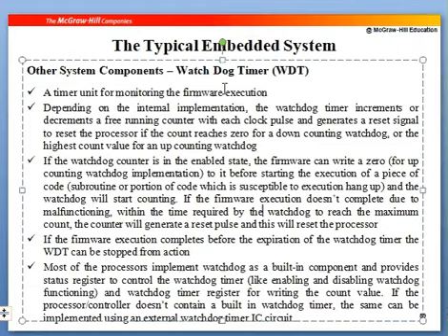This watchdog timer will be connected to the reset pin. So if the firmware execution doesn't work normally, and after some 10 or 15 seconds it is still not executing normally, it has been broken or hanged.